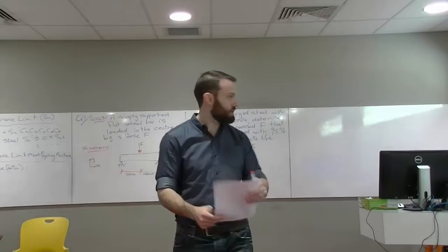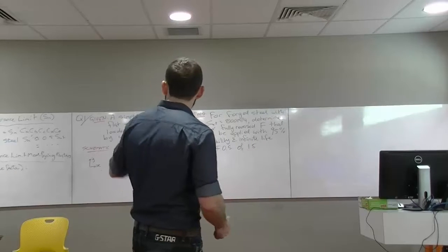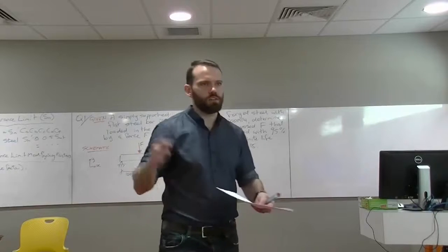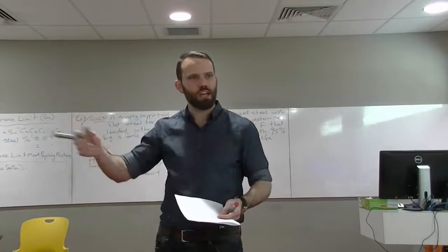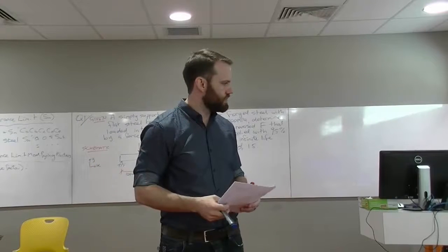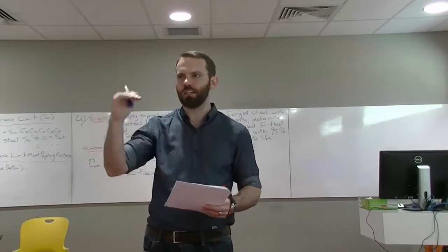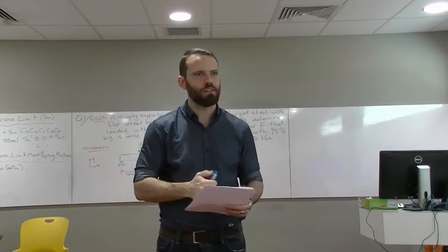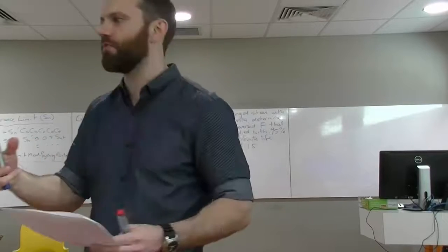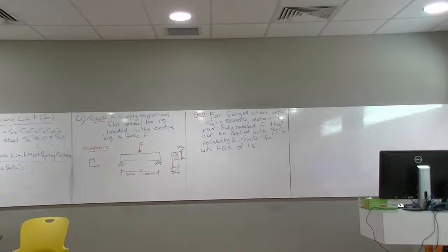What's our ultimate tensile strength here? 800, so Sn equals 400 times your 5 values, and you'll end up with an Sn result. Okay, so that's the way I like these to be laid out. That way you've got the assumptions and all of your information, your explanation of what you're actually doing in line there. So does that largely answer your question? Yeah.